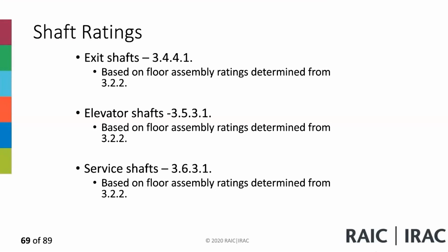You see Table 3.5.3.1. It tells us that for 2-hour floors, I have a 2-hour rating for elevator hoistways. For a 1.5-hour rated floor assembly, I have a 1.5-hour enclosure for my elevator. For 1 hour, it is a 1-hour elevator enclosure. So similar to that of exits, elevator shafts will take the rating of the floor assembly. If there's no rating, it defaults to 45 minutes.